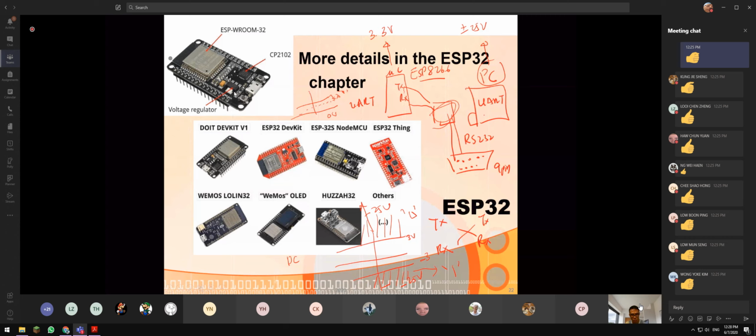But if you like to do imaging, and you want to get a cheaper board to do facial recognition to recognize objects, the ESP32 Cam is a very interesting choice. There are a lot of libraries out there. You can have a try, but remember you need an FTDI. You can't just simply connect the ESP32 Cam directly to your PC.